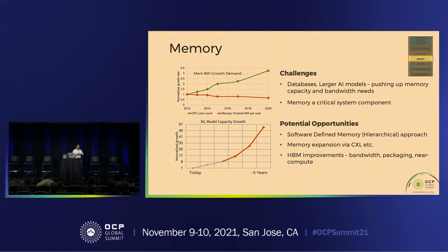This is the only way we can continue to leverage this. And looking at memory expansion, going beyond current technologies of building it on die, having expanders with CXL and other such technologies is another important direction which can unblock some of these innovations. And when we think about memory, it's not just the compute, it's not just the bandwidth and capacity. With HBM, I'll talk about briefly in the following slides, things like power and cooling are also becoming important.